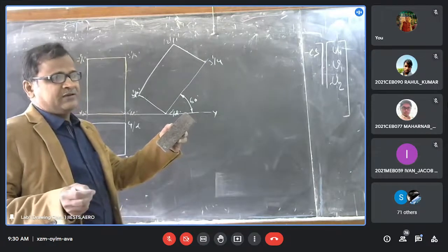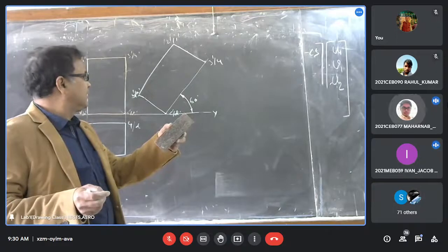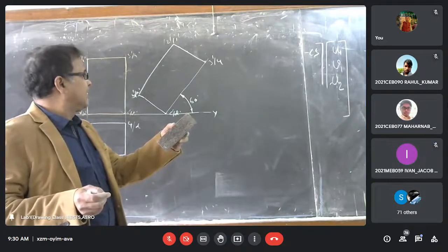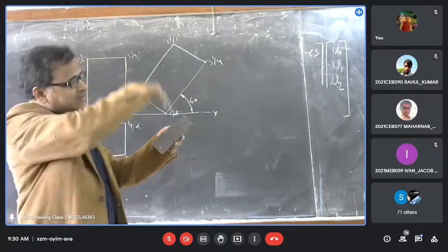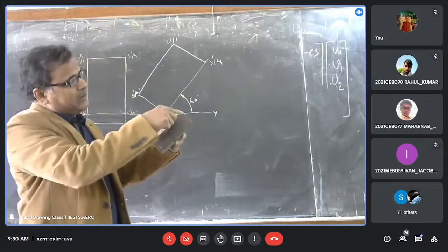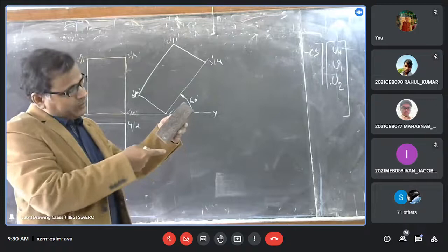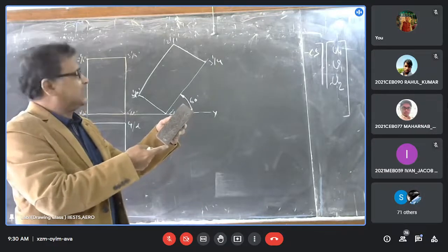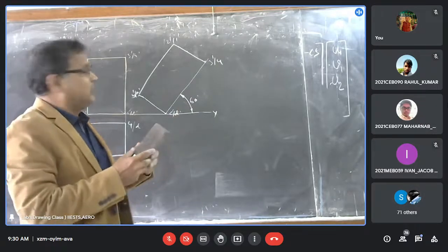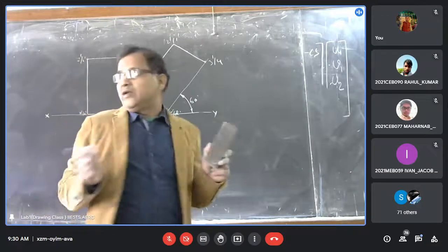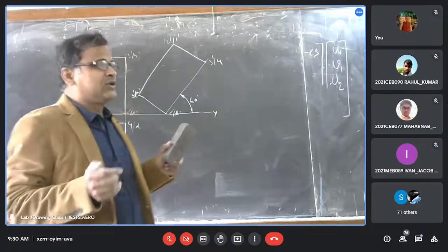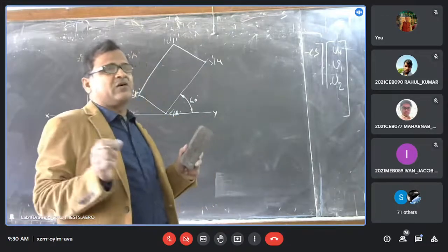Do you understand? Yes, sir. You can see all the edges. These edges overlap while you see this one and this one, the same line. But you completely cannot see the resting edge. Okay. So the edge you cannot see while taking some views, that edge should be a dash line or dotted line.